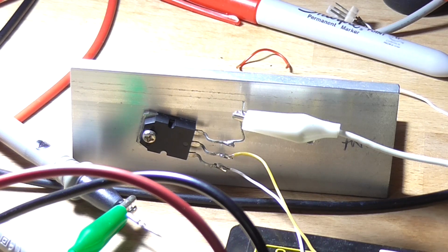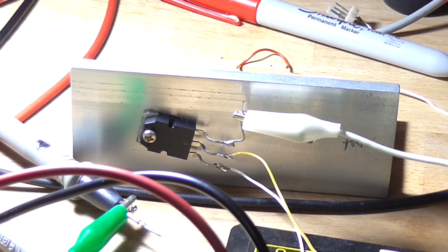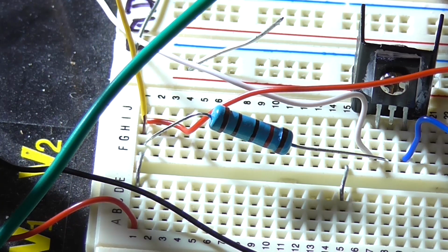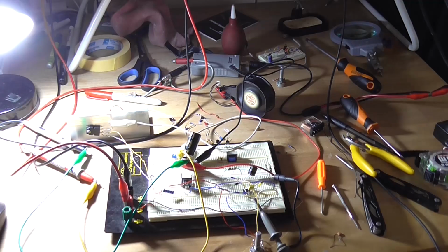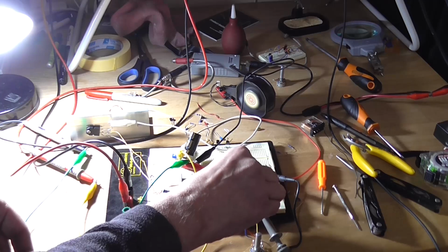I also have a TIP35C connected in Darlington as in the original circuit with the BD139, and just a 220 ohm 2 watt resistor there between the collector and positive of the BD139. Now it seems to work. However, let's do that experiment with the changing of the capacitor.